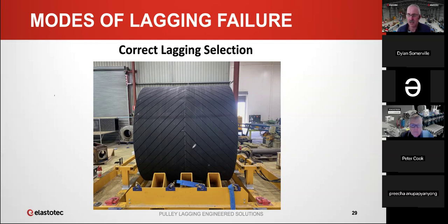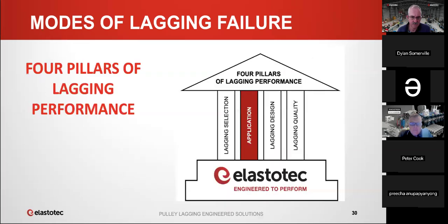That lagging was installed 2 years ago, and it's getting to the stage where it needs to be replaced. So we've gone from 4 weeks to 2 years. Unfortunately, not unfortunately, the bearings and locking elements are still completely serviceable. We actually need a lagging to last 5 to 7 years. So this is an ongoing project, and we'll talk more about that in the next course.